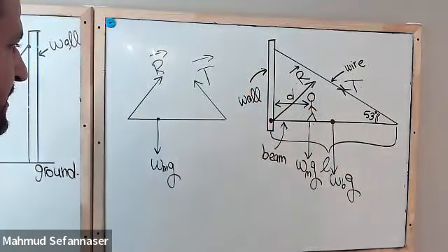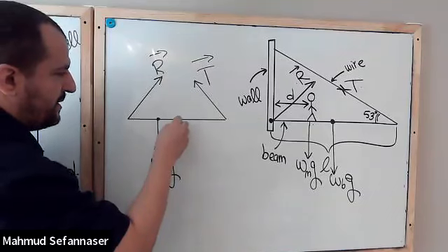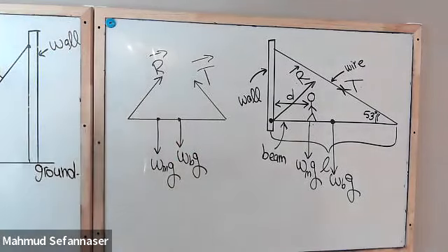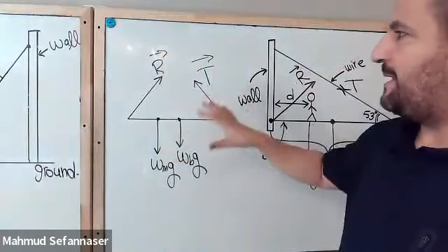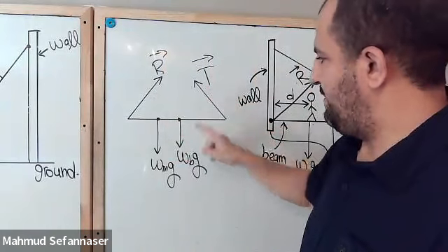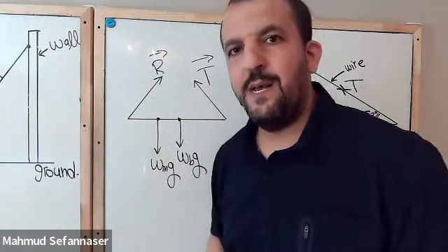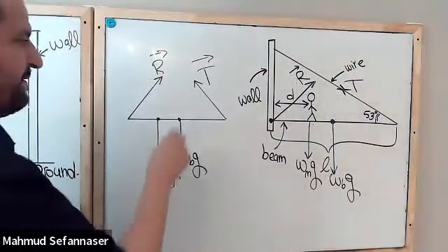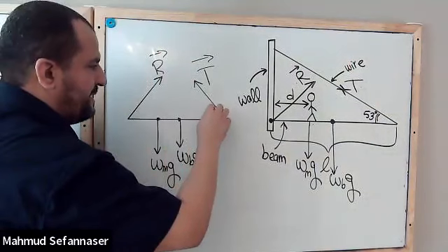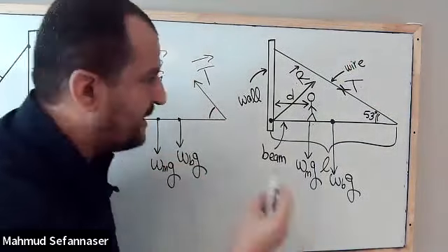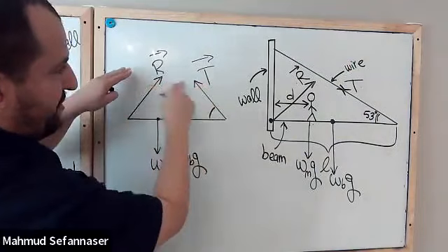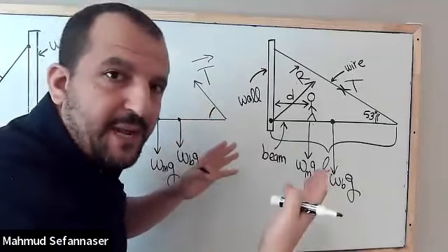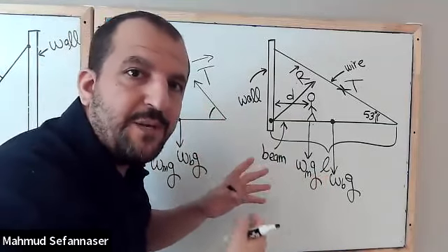Okay, so I will include that right here. So we have W beam times gravity. This is simply the free body diagram. So 1 force, 2, 3, 4 forces. What is the first thing that I need to do, guys? The first thing that I need to do is to know these angles, because I need to decompose these two forces. So I have X component and Y component, and that can help me, guys, to use the equation of summation over torque.